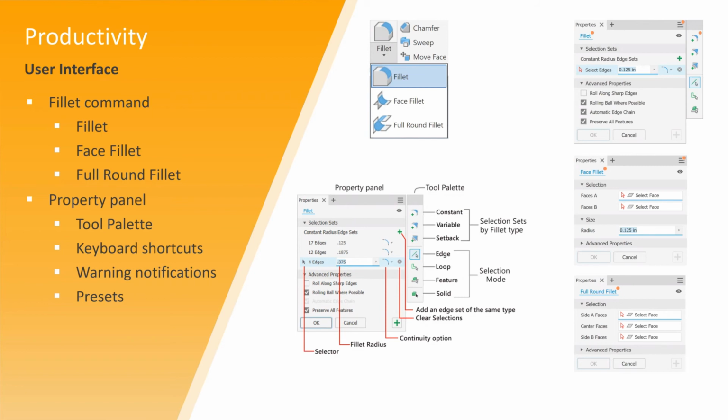So again, if you're opening a 2020 or 2021 fillet feature, those features will not change until you edit the fillet. So just maybe note that the change to the fillet feature in the browser will not update unless you go and edit the actual 2020 or 2021 or previous version fillet functionality.